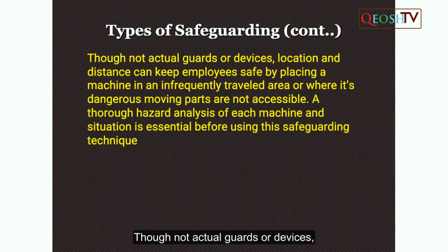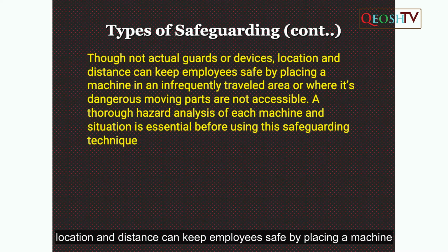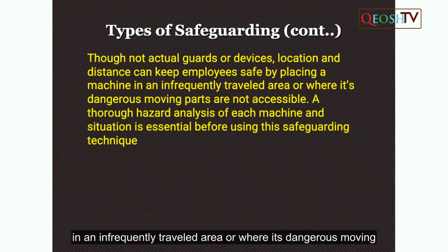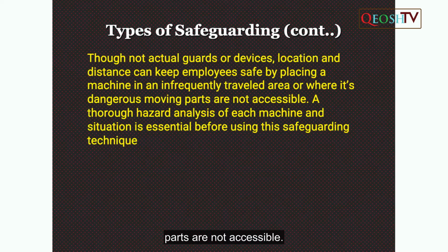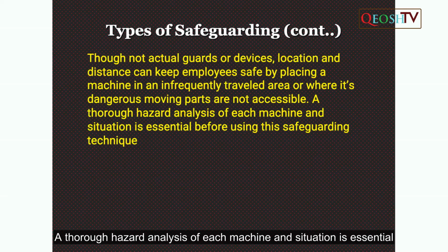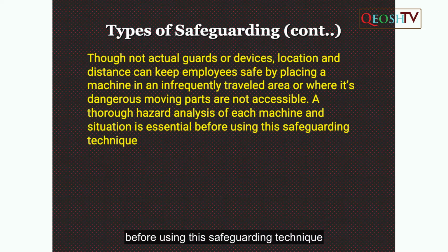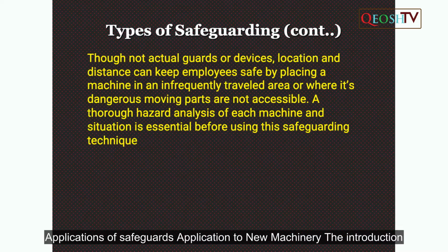Though not actual guards or devices, location and distance can keep employees safe by placing a machine in an infrequently traveled area or where its dangerous moving parts are not accessible. A thorough hazard analysis of each machine and situation is essential before using this safeguarding technique.